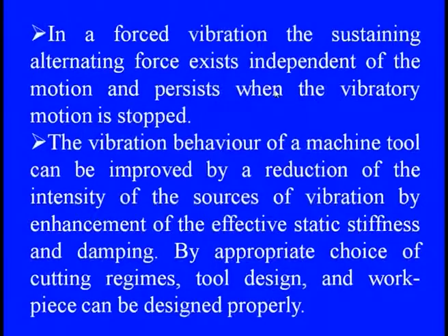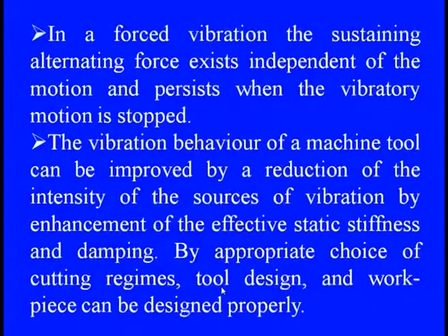In the forced vibration, the sustaining alternating force exists independent of the motion and can also persist when the vibrating motion is stopped, which is a significant feature for controlling the self-excited vibration. And the vibration behavior of a machine tool can also be improved by reducing the intensity of the source of vibration, by enhancing the effective static stiffness and damping together.